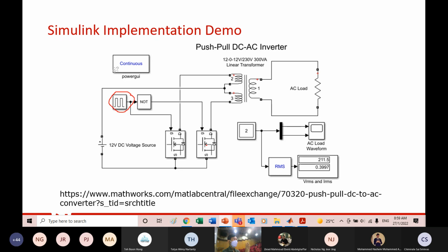That's why it's one push, one pull. You cannot two pull, two push. So that means when I have a positive here, this one will be inverted. And you can see these are the same topologies and the same AC load.